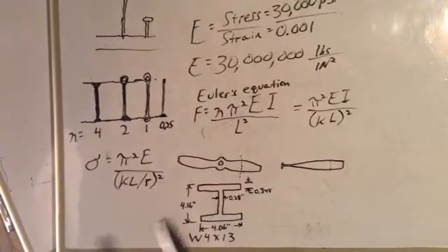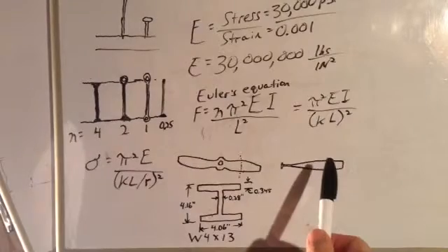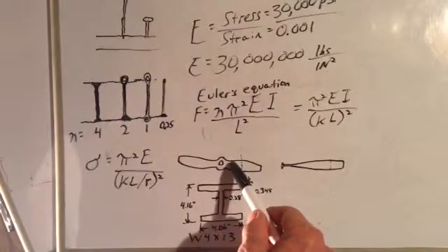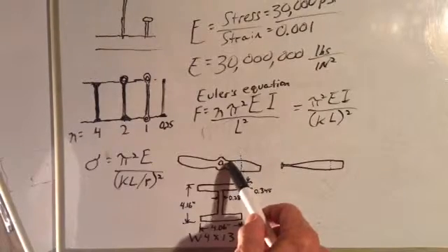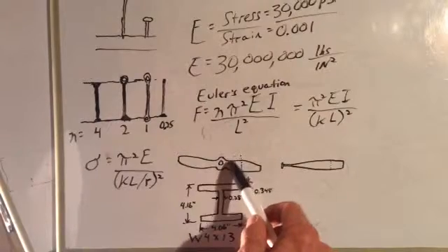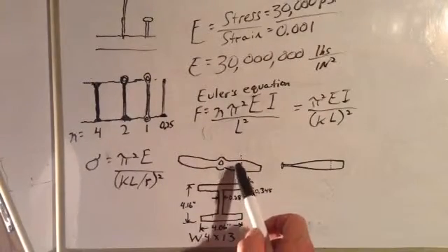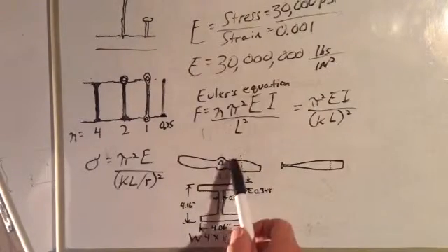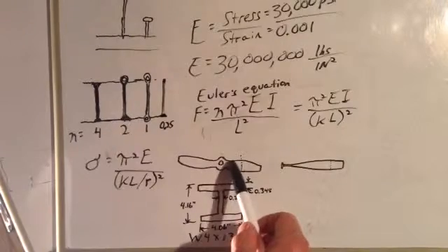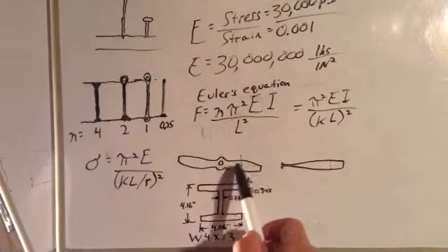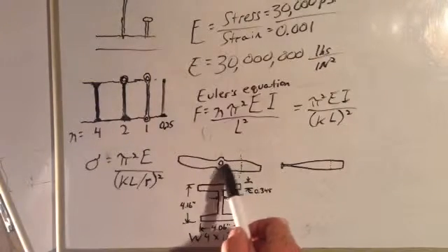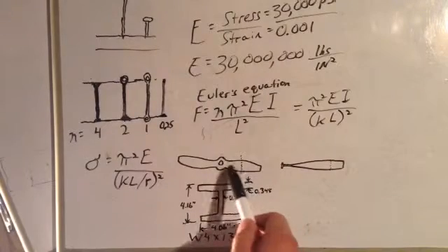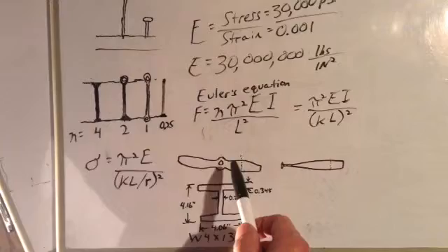The propeller and baseball bat here, they have mass radius of gyration. If we look at one teeny weeny increment of mass, let's say we pick a little piece of wood that weighs ever so slightly, about like a grain of dust, an infinitely small mass of wood from this propeller, and we multiply that mass times the square of its distance from the center of this propeller shaft. And then we do the same thing for every other little infinitesimally small unit of mass in this propeller, and we add all these little masses times the squares of their distances from the rotating axis together. We sum them all up. Then we have the mass moment of inertia.